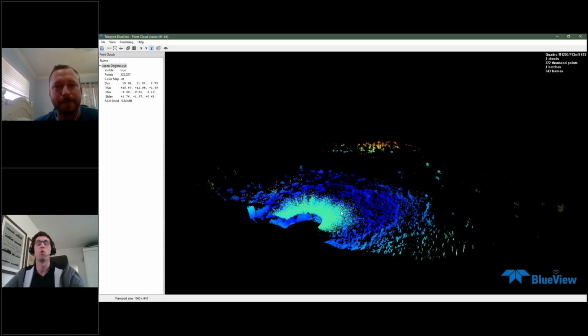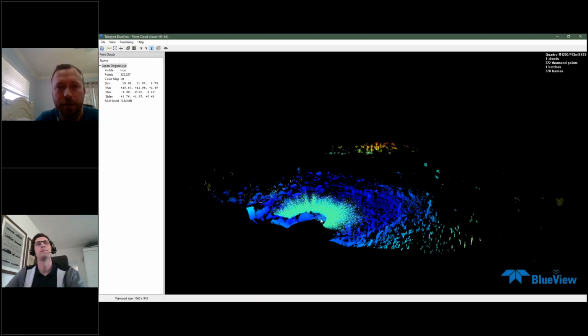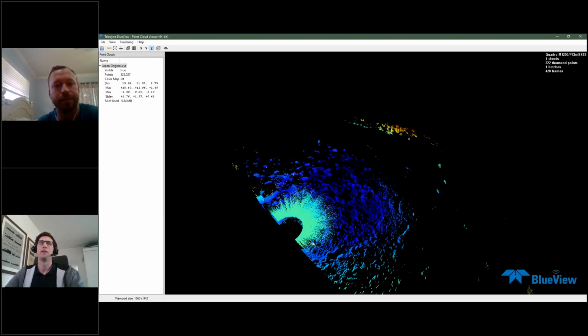So we're doing one detection per beam, right? In this case, the strongest detection along each one of these beams is actually on this floating sediment or whatever it is. I assume it was quite large to be picked up, but it was actually aeration. So it was bubbles. Flowing by, because just upriver it was rocky, so it was really roughly flowing, and it was causing aeration in the water, which is a really good acoustic return. Yeah, aeration is the enemy of the sonar.